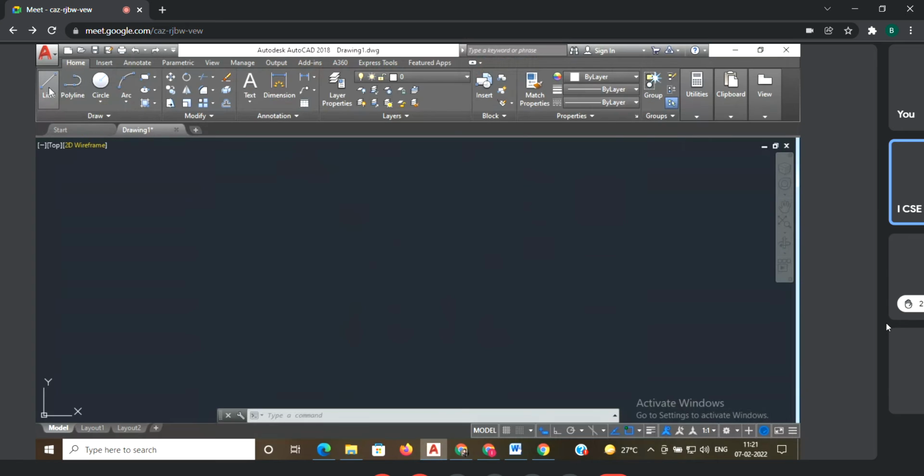First I will select the line command and draw a horizontal line. Okay. Otherwise I will draw on the right side, no problem. Ortho on. Okay. How much? 65. And one more thing is, sometimes when you start your diagram, you won't get this command ribbon.